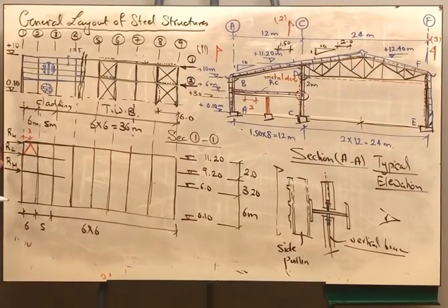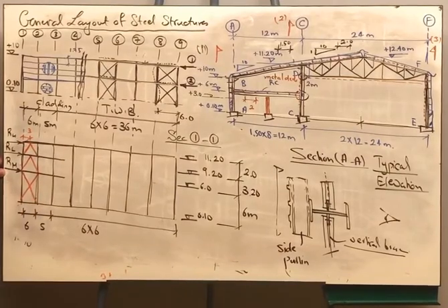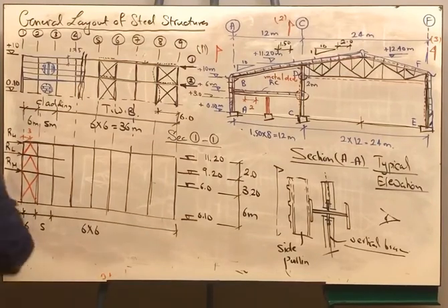It is between 30 and 60 degrees. The same thing. Here you are having 3.2 and here you are having 6 meters. Again, I am going to have a K truss. And this is 6 and 6. Excuse me for the scale. Then I can use a bracing. It will be ideal because the angle will be 45 degrees. Of course, this will have to be repeated.